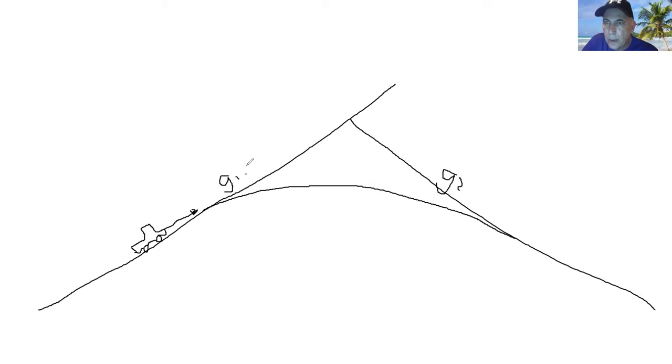So one would be a percentage, a slope going that direction. The other one would be a slope going the other direction. So you can see here, this would be that direction, and this one would be this direction. So in this situation, we'd have a positive grade going in, a negative grade going out. Now, how do you determine which way is positive or negative? It's really a function of stationing of the highway. If the highway is progressing this way as we go along, then this would be a positive slope going in and a negative slope going out.